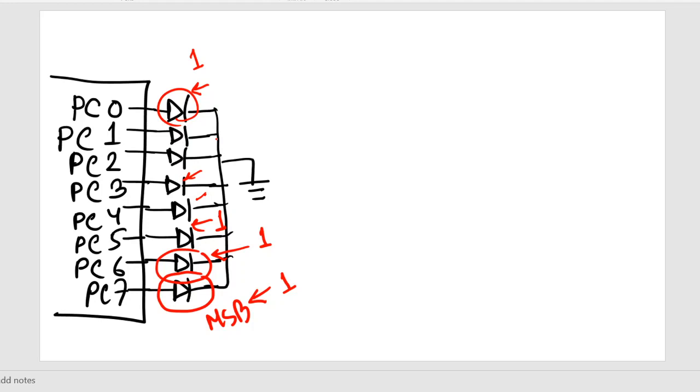I have already said that there is particular syntax when you are writing code in C, but in this lecture, whatever I have covered, you have to first declare port C as output pin. That means you have to write DDRC, write some particular data in DDRC, and then you have to send data to port C.